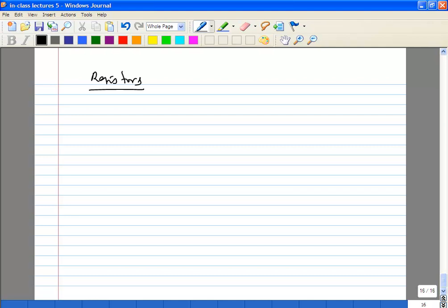So let's look at the different kinds. Polysilicon resistors, whether silicided or non-silicided, will typically have very small values. Obviously, the lowest values will be your metal routings themselves. They'll give you up to probably a few ohms. These can probably give you a few tens of ohms.